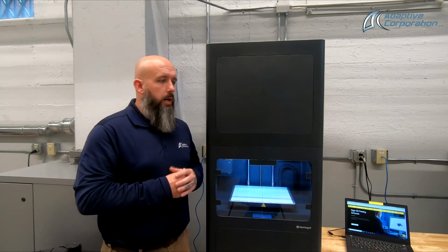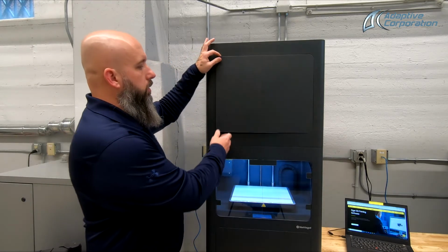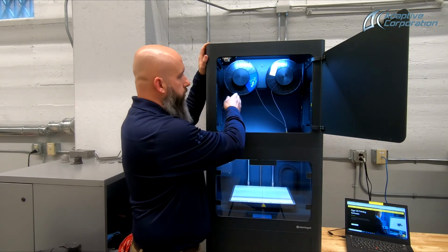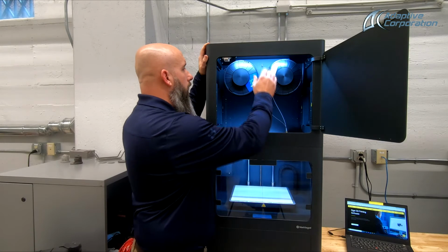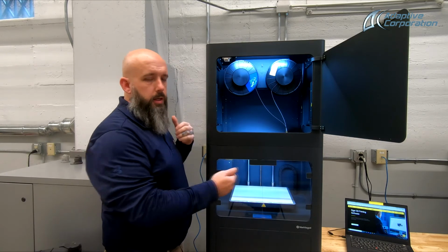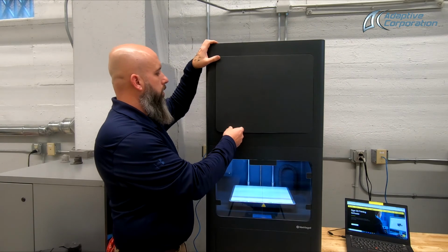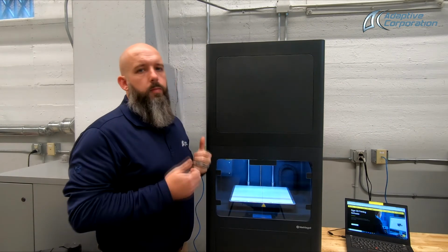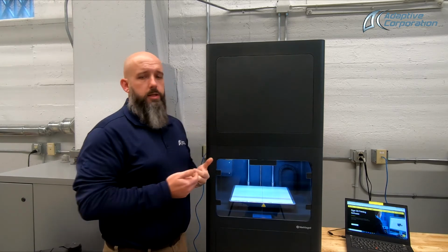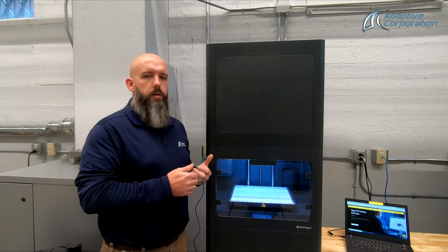Okay, before we hit print, I'd like to go over a few more details with the Metal X printer itself. And the way it works, it uses a two-part system. You can see we have two spools here, one of the actual material we're going to use, which is 17-4, and the release material. This works in conjunction for us to be able to remove supporting materials as the part may require them. That being said, the metal printing system is capable of using multiple types of material. You can use stainless steels, tool steels, copper, and Inconel, and there are currently other materials in development.